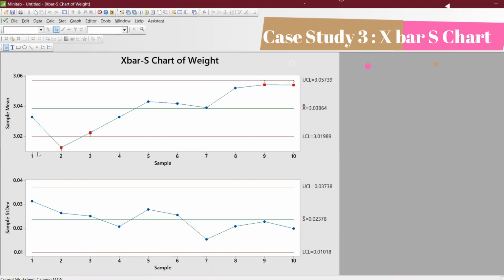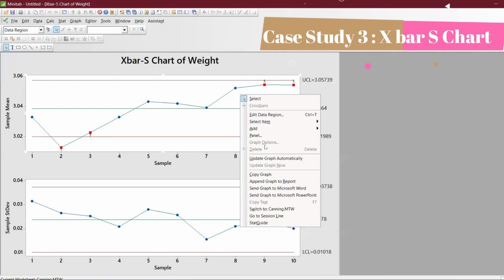You can see here that each sample has 10 in the subgroup, right, and the only thing is no outlier is there on this side, but there is one in sample two that has an outlier, at 3.303, and the interpretation, rule number 5, is failing, and you can see what rule number 5 is.